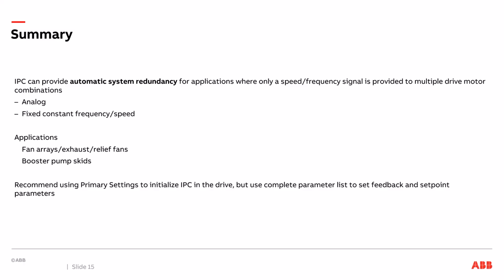Well, I first recommend using primary settings to initialize the IPC setup in the drive so the drives are talking together. And then I discuss going into the complete parameter list in the drive to program some specific parameters such as the feedback and set point in group 40 of the drive.